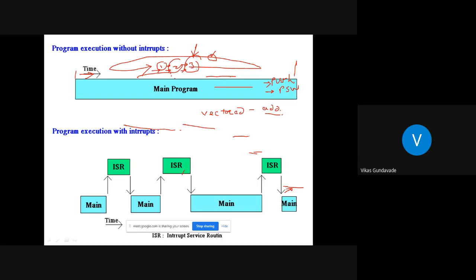Now in loop mode, if the microcontroller is executing task 2 and an event is generated in task 1, then that event will get served only after complete execution of task 2, task 3, and when the microcontroller returns back to task 1. That event will get served by the polling method.